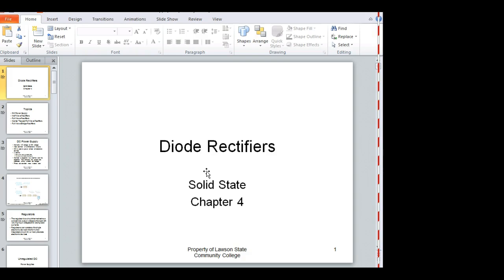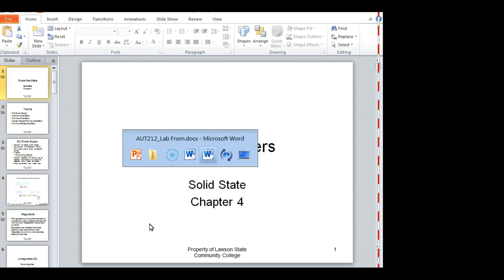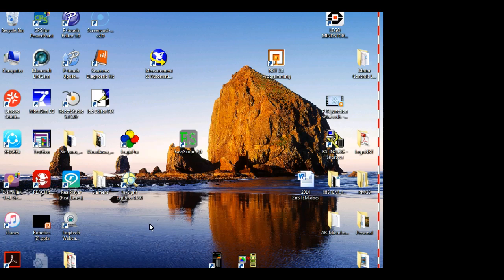So it produces motion. So if I bring another conductor in close proximity to this conductor, it will induce a voltage in it. Now, what determines how much voltage we induce is how we couple it. We got to have real good coupling. So that's why, let me bring up my camera, that's why on these magnets we don't use regular wire. We use what we call magnetic wire to get a real good coefficient of coupling.